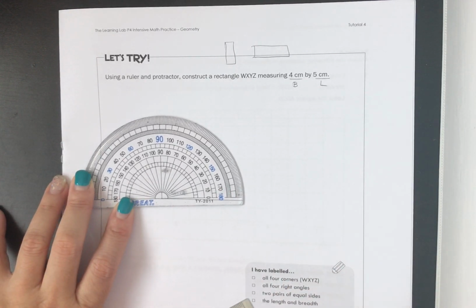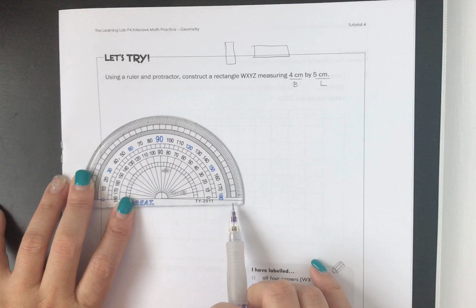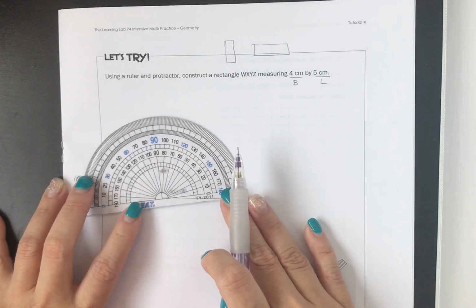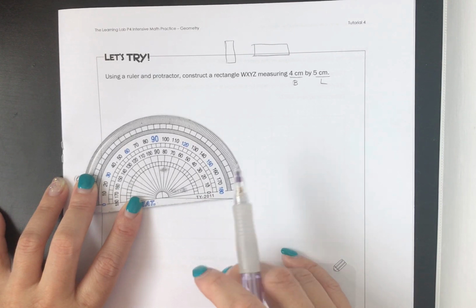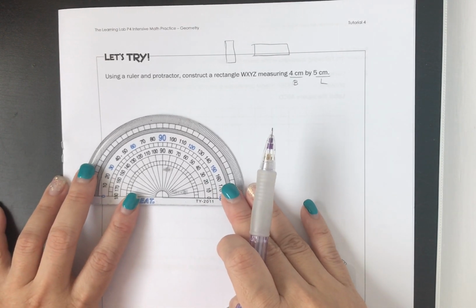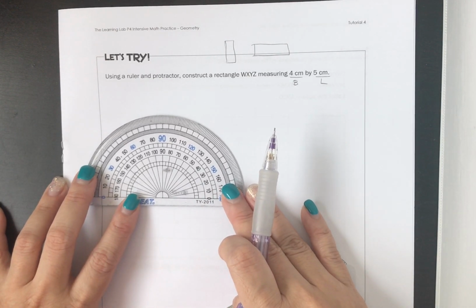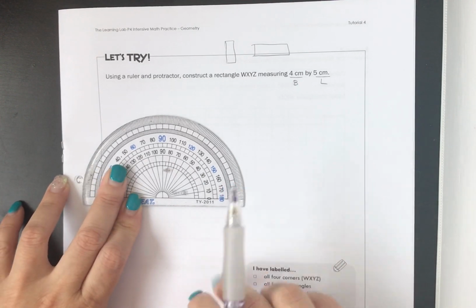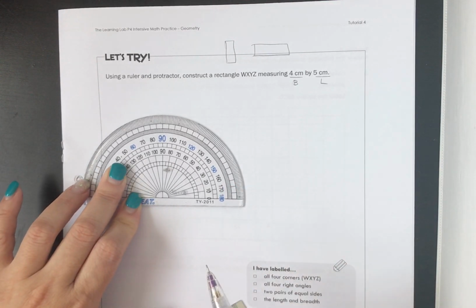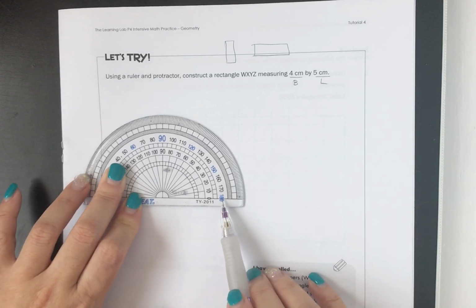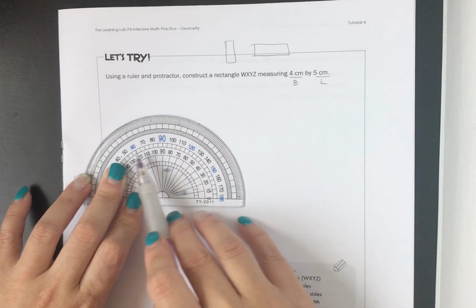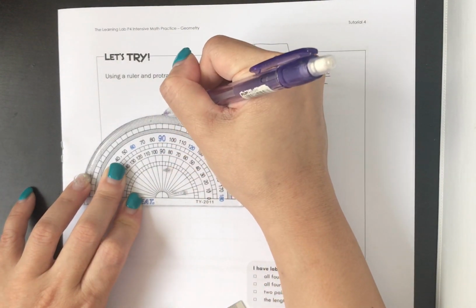Now, what I'm drawing right now is not well aligned. You can see the line here is not against the bottom baseline. So make sure your baseline is accurate to the line drawn on the paper. Now, the good thing about drawing right angles is you don't really need to look at the scales, because either scale that you use, the 90 degrees will be here.